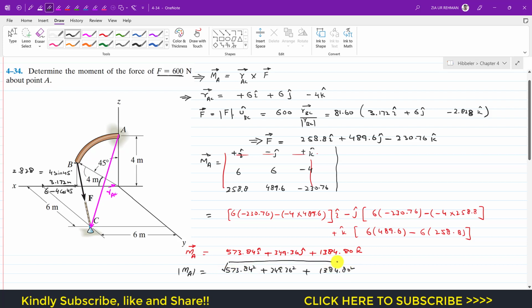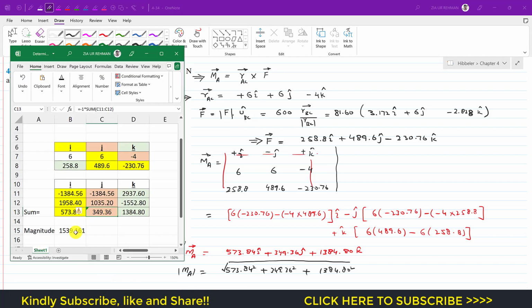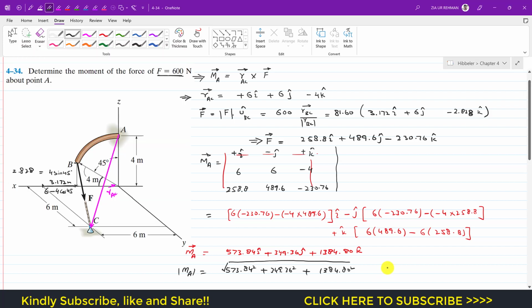If we find this, that will give us this magnitude, which is 1539.16. The units will be, since the force is given in newtons and the distances are in meters, Newton meter. Similarly, the units of this will also be Newton meter.